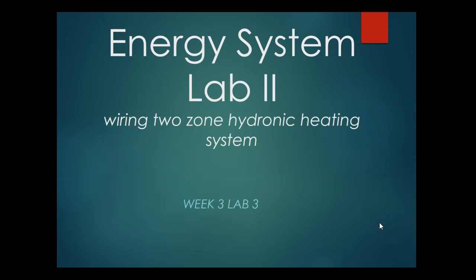Hello, welcome back. This is Professor Khan, and this week is week 3, and we will be wiring a two-zone hydronic heating system. After week 1 and week 2, week 1 we wired the primary control, week 2 we connected the primary control to an aquastat, and this time we will add a switching relay so we can connect two zones into a hot water system, which is a very common thing.